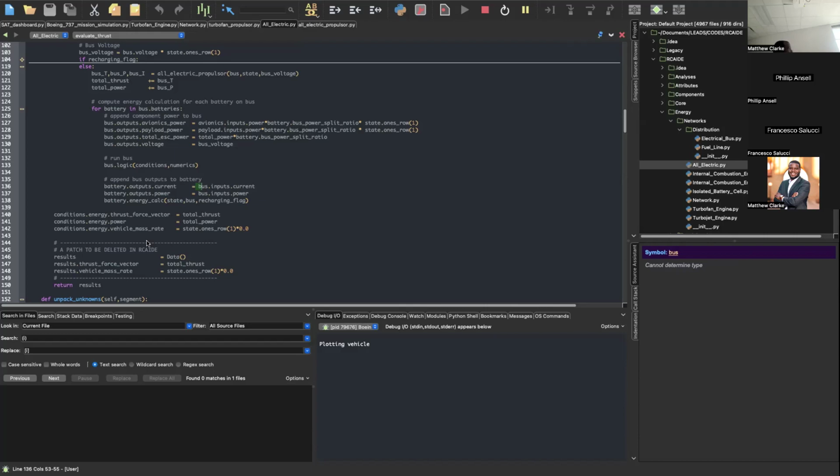So I think if that happens, and let's say you have a battery pack that fails, I don't think we should fly that flight again as the aircraft designer. So you just say at that point the mission is over. You shouldn't fly the next flight, but you should be able to land on that flight, right? That's what the battery split ratio is for, particularly. You can change the split ratio to change how much energy is coming per battery. I think that is something RCAIDE should decide, not the user. That will be running an optimization.